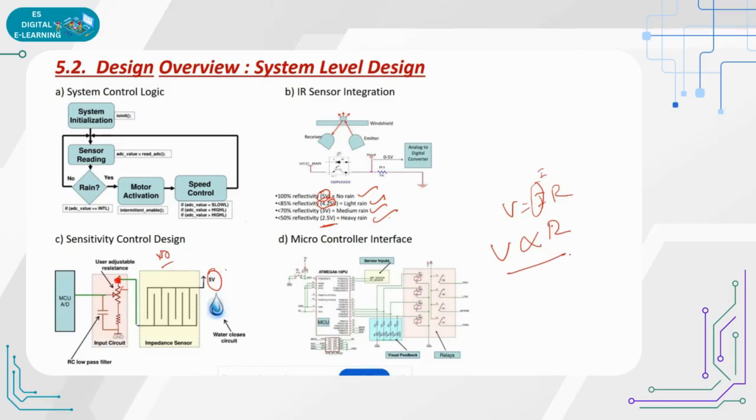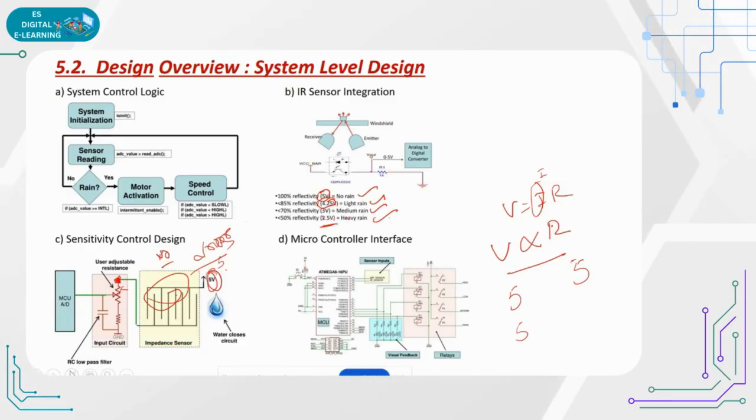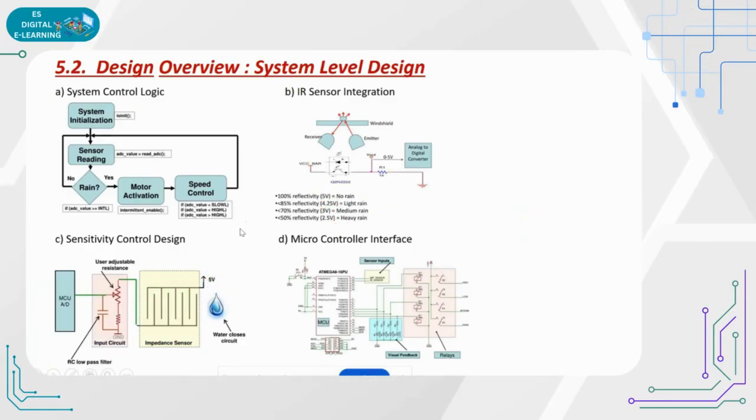Now the resistance is high, which means here we have the voltage of 5, here it will be 4. Whenever the voltage is dropping down, whatever voltage you are supplying, 5, in between it is dropped. Due to the rain sensitivity, or reflectivity, this voltage supply will also change. So this is how the sensor is internally connected, and internally it will be varied.